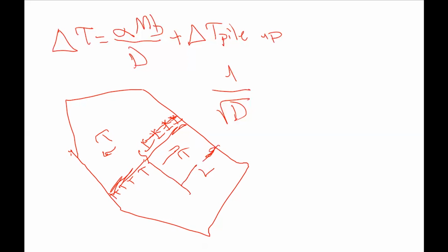When dislocations generated by a Frank-Read source approach obstacles on the slip plane, they often pile up. The obstacles include grain boundaries, any second phases, like in superalloys, we have gamma and gamma prime phase, phase boundaries, and any sessile dislocation.